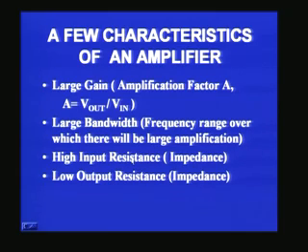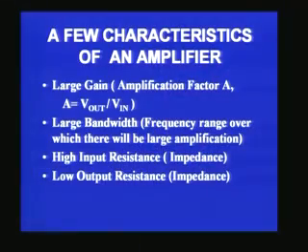High input resistance should be there so that it does not load the input, and low output resistance should be there so that it can drive any load at the output. About these characteristics we will discuss in detail at a later stage, and therefore I just want to mention to you that whenever I want to construct an amplifier I should make sure that certain basic characteristics are built properly into the amplifier so that it can be made use of very well.